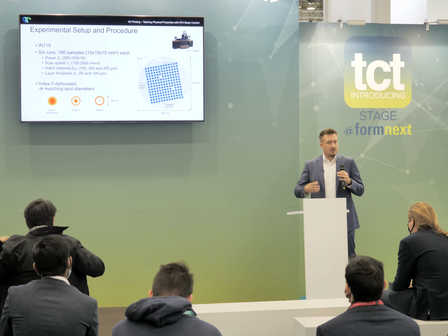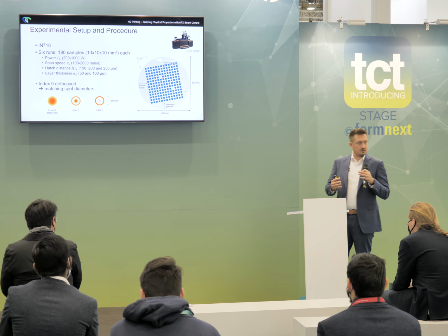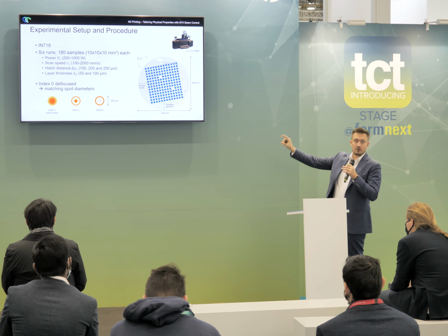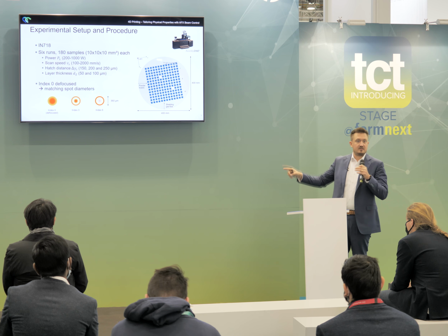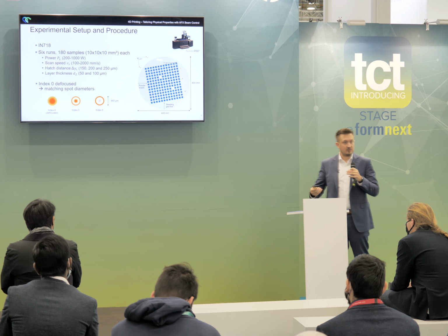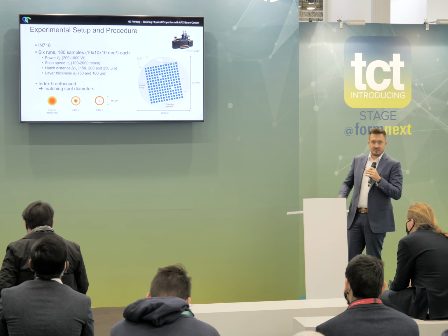In order to enable a more concrete comparison between the standard intensity distribution and the ring mode, we defocused the Gaussian beam so that the outer diameter is similar to what the ring mode provides. So we have no influence of significantly different spot diameters in that.